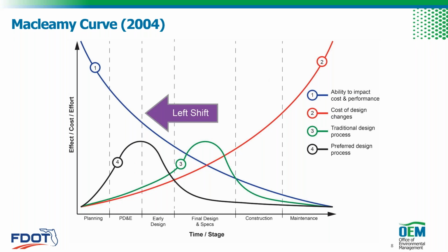That is a GPS device, and it is communicating with whatever they've triangulated in the area for their control, and it's telling the blade, the screed, or whatever the apparatus is, where it needs to be in relation to the world in order for it to create or grade to that design that's been produced. So very good question. I'm sorry I didn't give you that earlier. Yes, AMG is automated machine guidance. Thanks, Catherine.